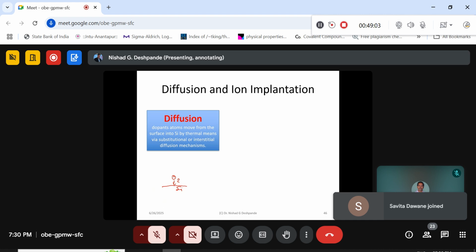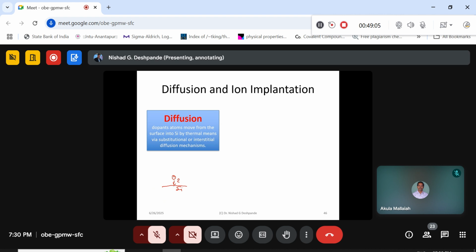It starts to interact with the silicon surface, it moves inside, and once it moves inside, it will start to have a reaction with the silicon so as to form silicon dioxide here. So the first process is an interaction process. The second process is a diffusion process, wherein the actual bondings will take place to form silicon dioxide.